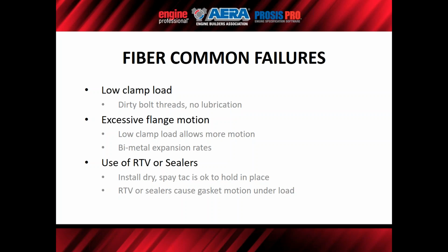Again, that RTV will cause flange motion or gasket motion in between that flange when it gets clamped up. Again, just picture yourself squeezing a watermelon seed between your fingers. And that's basically what you're doing with RTV on both surfaces. So install it dry unless otherwise told.